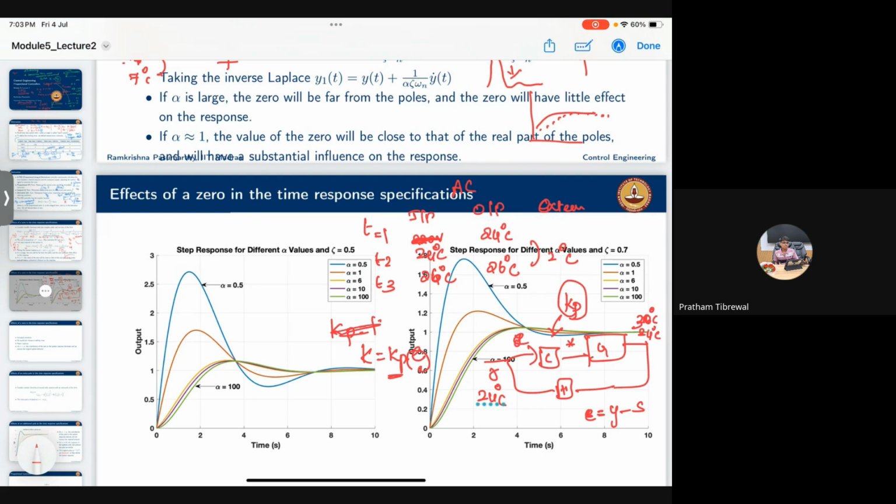But if you have an integral controller along with it, at the first instance, that will also behave as a proportional controller. There will not be any change, because at the first instance the error is 0, right? 24, 24. Integral won't do any action. At the second instance, it will see there is a 2 degree increase in the temperature, 24 to 26. So already there will be some proportional gain, and this integral controller will also add some gain.